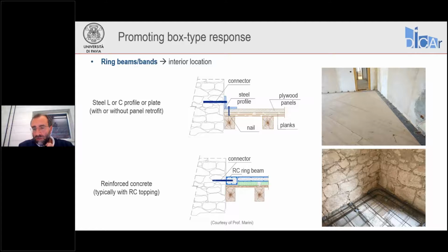You see in the photo, you can recognize the steel mesh of the diaphragm topping, and close to the boundaries, you see those larger diameter bars that are just the longitudinal reinforcement of the chords and collectors of the diaphragm, without the need of any transverse reinforcement.